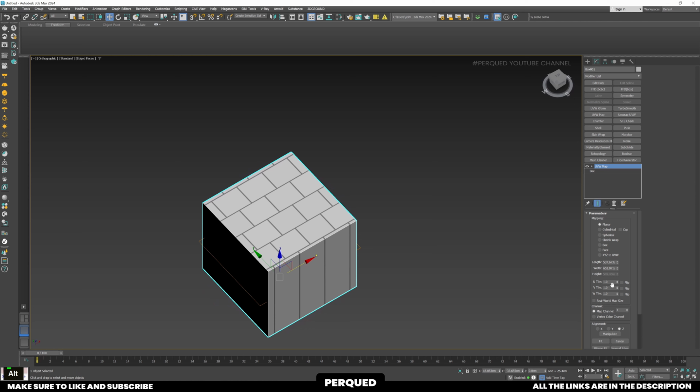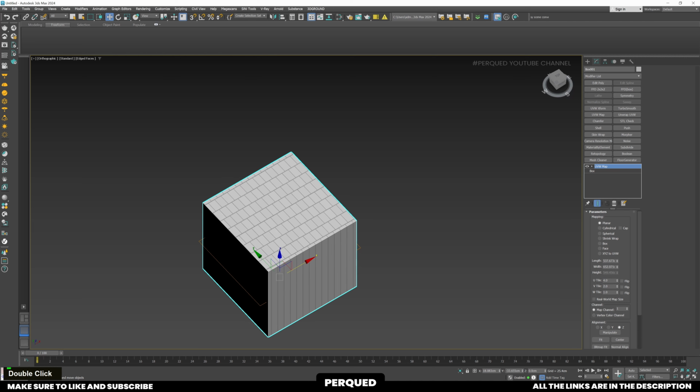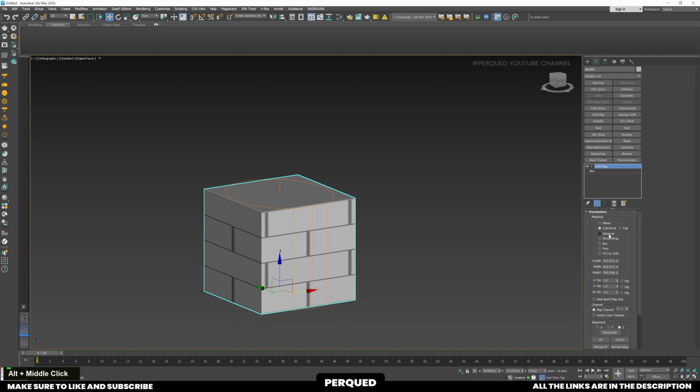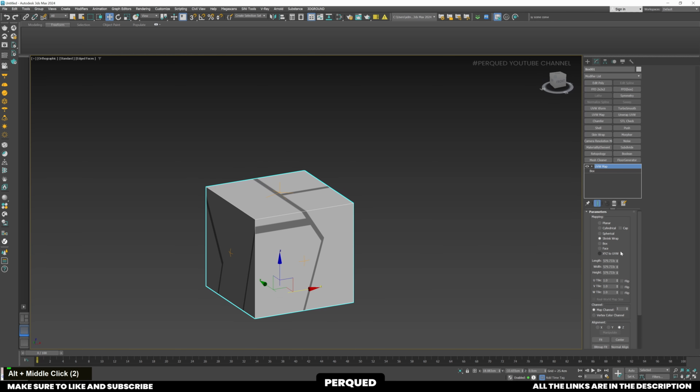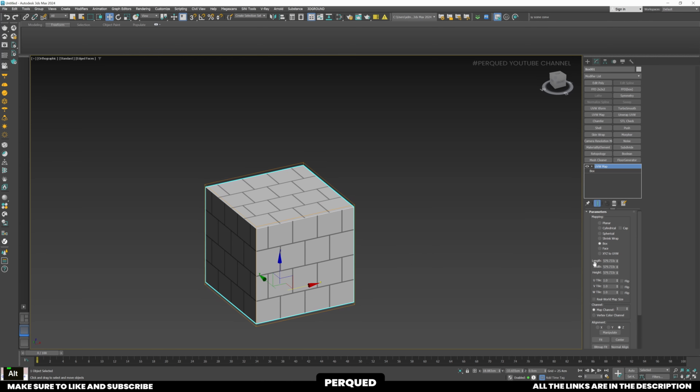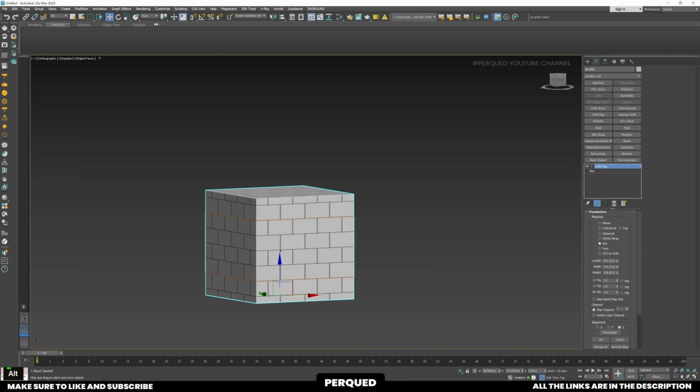You can also use the multiply method from tile to make a multiplied result, like you put 4 here to make the mapping multiplied by 4. You can also flip the mapping from here. There are different types of mapping here, like box, spherical, cylindrical, and planar. Right now we have box, so let's choose box mapping. Now you can set mapping like this.